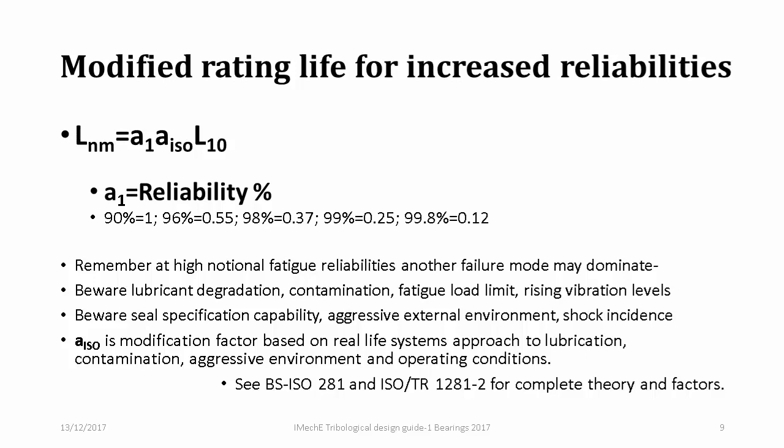However, if you design for very high notional Hertzian fatigue failures, other modes of failure might actually dominate. If the lubricant becomes degraded, then the surface initiated fatigue that I already mentioned can occur. Contamination does the same thing. There is a thing called a fatigue load limit we'll come to in a moment, and rising vibration levels can also mess up the lubrication. Seal specification capability is important.